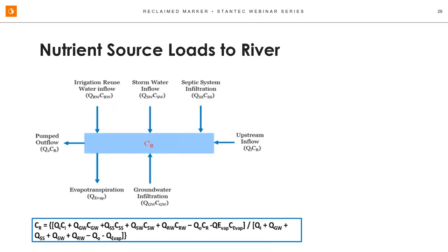So we went ahead to do this mass balance. And of course, the beauty of this is with the iohexol only being present in the reuse water, which we've labeled as RW, then basically most of these other terms will drop out because the concentration will be 0 for the iohexol.